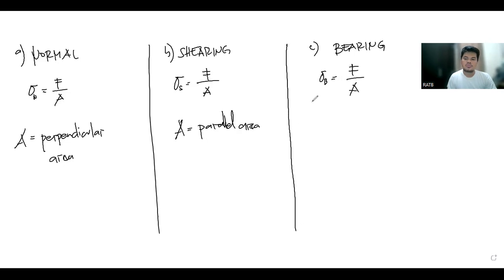And for the bearing stress, we define A as the projected area. Later on, we'll show some figures to illustrate the difference between the normal stress, the shearing stress, and the bearing stress.